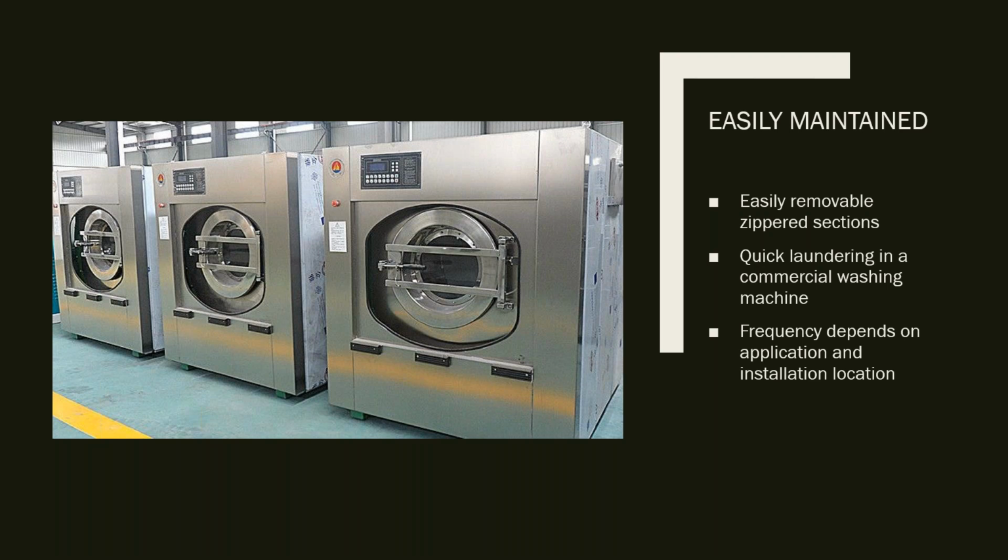All you have to do is take your standard detergent and add a sodium percarbonate additive to it. This will clean and disinfect the diffuser without damaging the fabric or the color. So if you think industrial strength OxyClean, that's what you would use in order to disinfect the duct. And yes, it does kill viruses like the coronavirus.